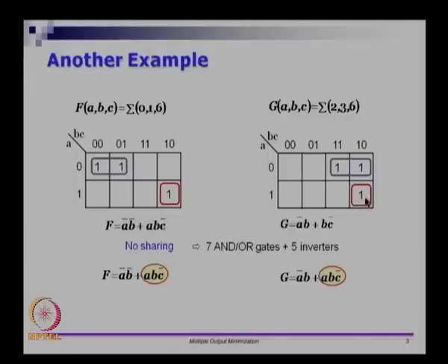And this is interesting. So when I talked about K map, I always said you should go and maximize the number of ones that you are grouping, and the argument is if you maximize the number of ones that you are grouping, the number of literals go down, and therefore the number of AND gates will go down if you are doing a sum of products. So if I group 8 ones together, then I am knocking off variables, right. So this is something that we saw earlier, we will knock off variables if we group 8 ones together. However, here I am making a case for not doing maximal grouping.